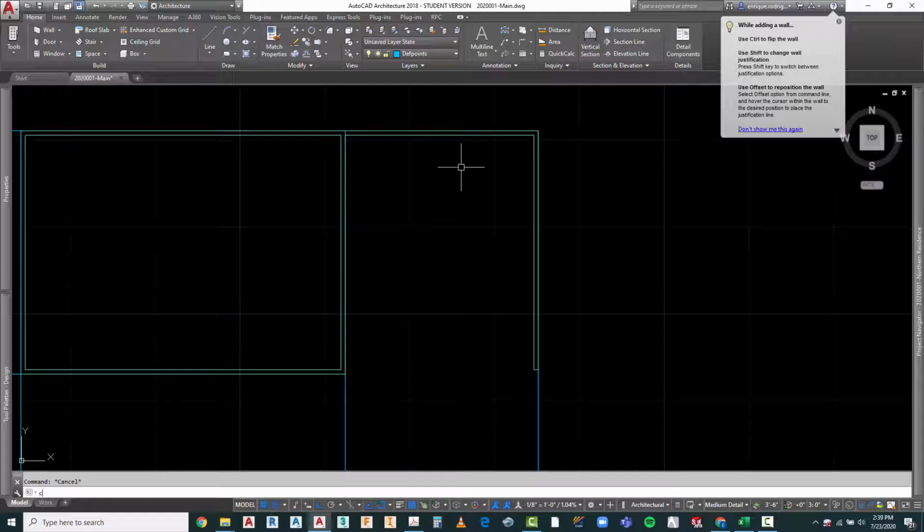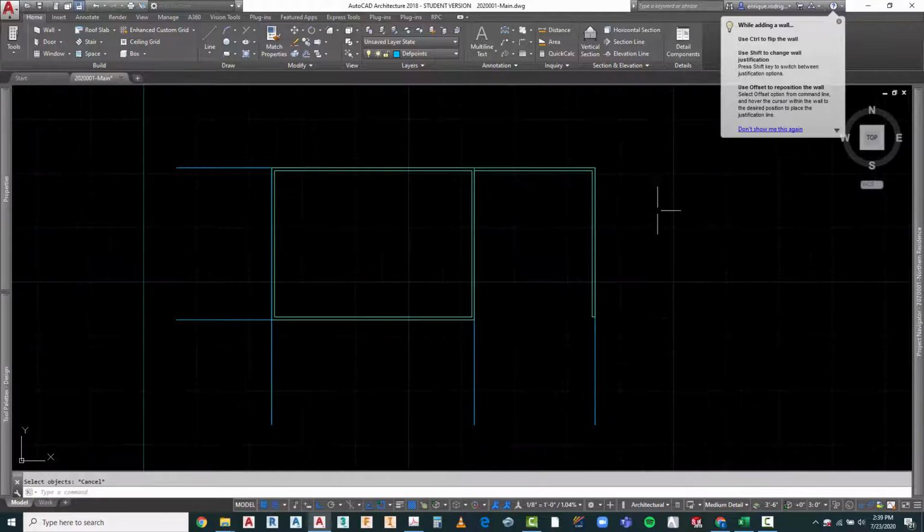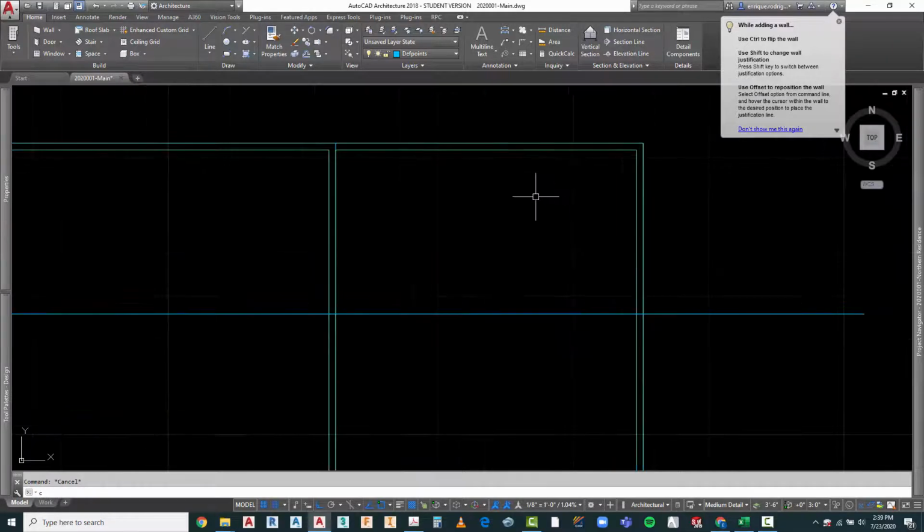So if I just wanted to do it by math, I could say, okay, we've got a 6-inch wall, and they want it to be 12'4". I need to copy this a certain distance over, but I'm just going to copy this guy down 12'4". I'm going to grab it by the grip here, and copy this guy